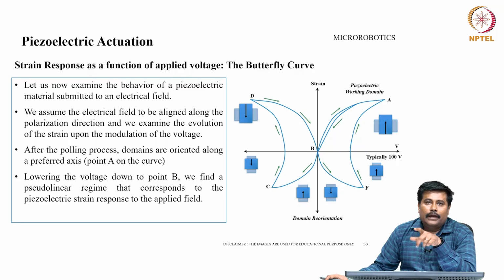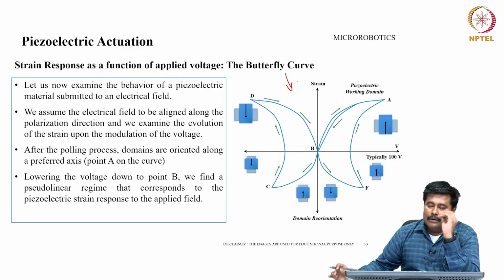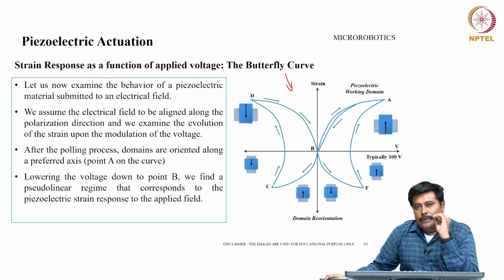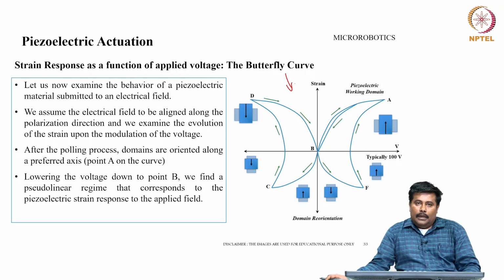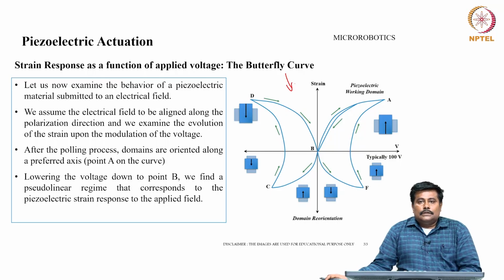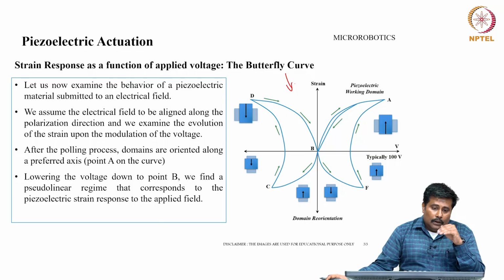As far as the strain response as a function of applied voltage is concerned, the butterfly curve is one of the key characteristics to investigate and quantify a piezoelectric domain. Ideally, the plot is drawn between the strain and the voltage. In order to examine the behavior of a piezoelectric material submitted to an electric field, we assume that the electric field is aligned along the polarization direction, and we examine the evolution of the strain upon the modulation of the voltage.